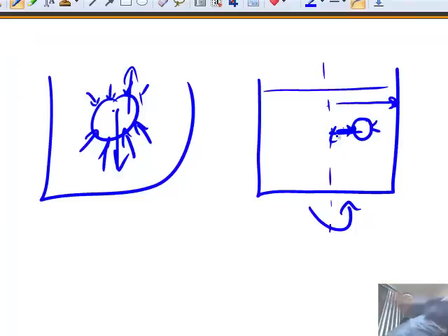Okay. I don't want to solve all the problems. I want to solve a few problems, show you the path, give you some ideas, and then I want you to look at some of those problems. So, a pressure distribution in a static condition in a centrifugal force field. The equation goes something like P equals P0 plus rho omega squared r squared over 2. You can open up Bird, Stewart and Lightfoot. They have the solution in there.